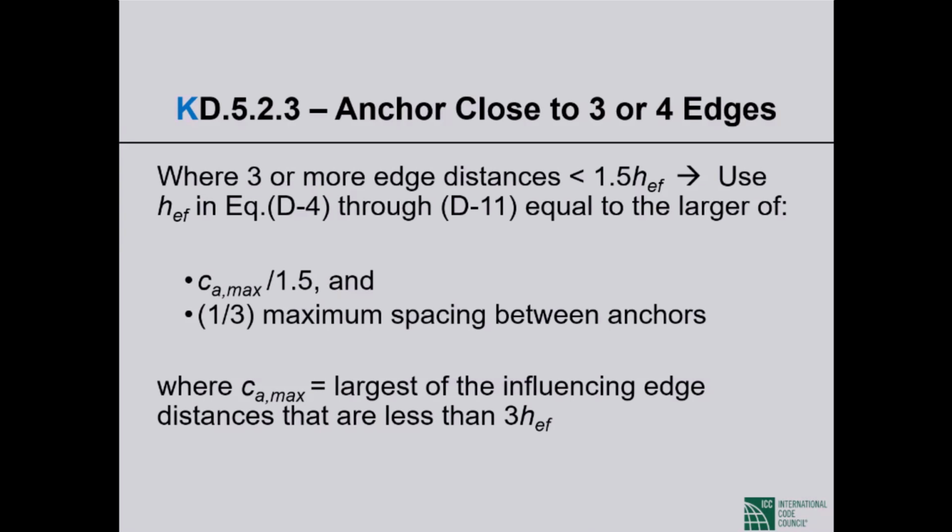Now, another complication. Where 3 or more edge distances are less than 1.5 times the effective depth, we use a reduced effective depth in breakout strength computations.